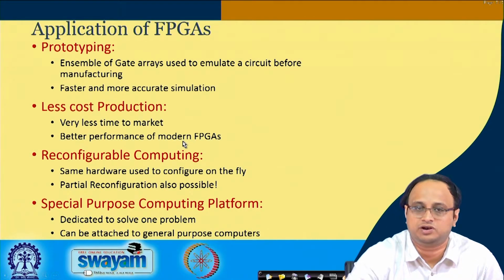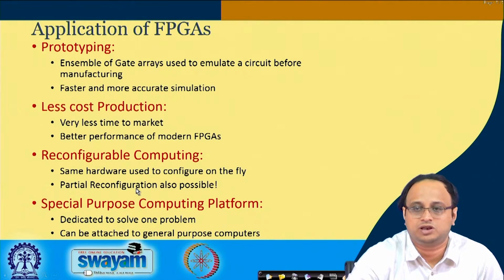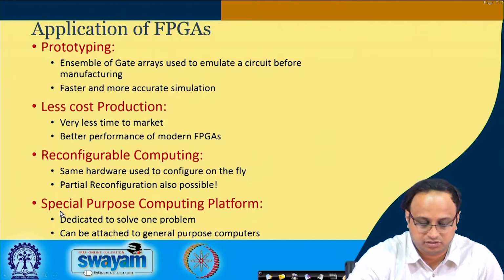FPGAs nowadays are pretty advanced. You can really develop competing technologies on FPGAs as well, because of various dedicated blocks that they have, like DSP blocks, multipliers, and so on. Another thing, as I already said, is that it is reconfigurable. You can make the same hardware reconfigure, and also reconfigure on the fly. With techniques like partial reconfiguration, you can do dynamic reconfiguration, and that is a huge advantage which FPGAs bring, particularly in the context of things like IoT, where you probably need to change things very rapidly.